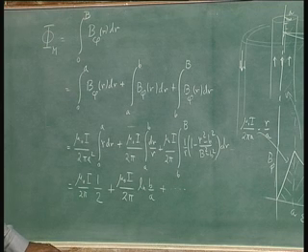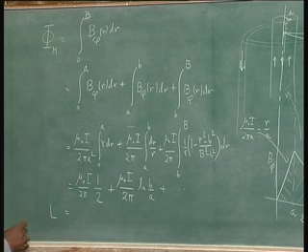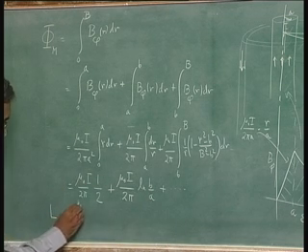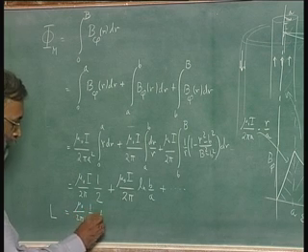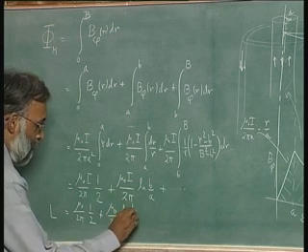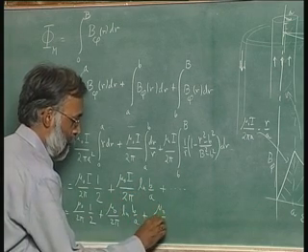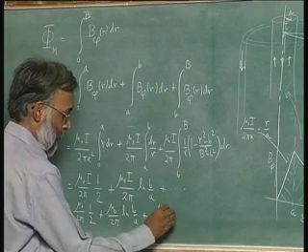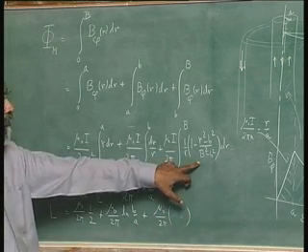Now, when I divide by current, I am going to get the inductance. So, if I divide by current, I get mu naught over 2 pi times 1 over 2, plus mu naught over 2 pi log b over a, plus again mu naught over 2 pi times a complicated mess of terms due to this integral.